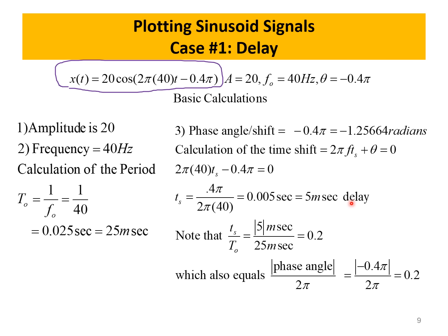The signal is 5 milliseconds delayed, so the peak is delayed by 5 milliseconds, going to the right this way. So this should be the original one, right? But because it's delayed, the peak will be here, and the distance between the two is the 5 millisecond delay. Now the time shift over the period T here should be 0.2. We care about this, and that.